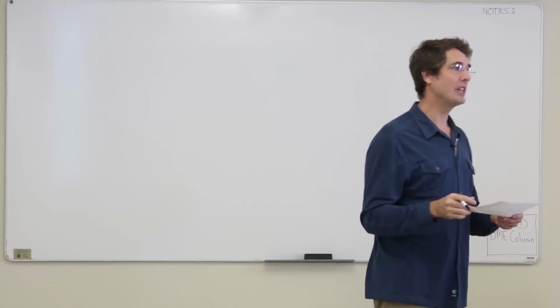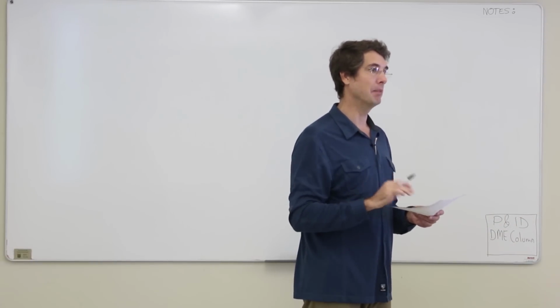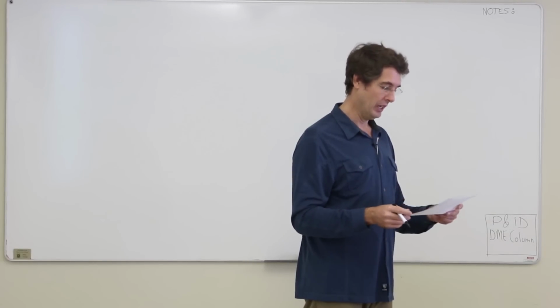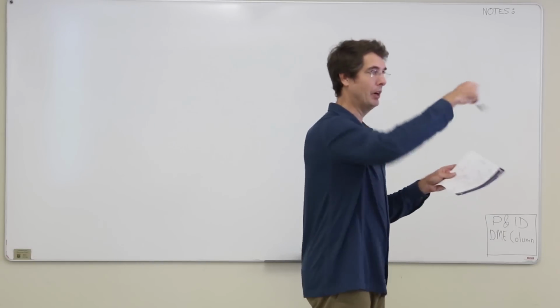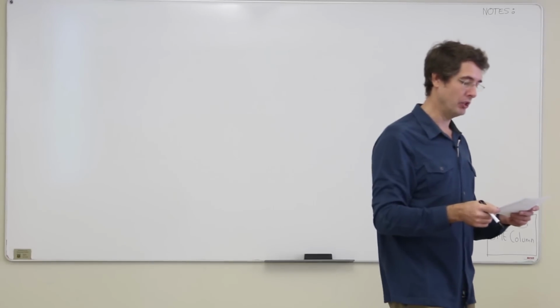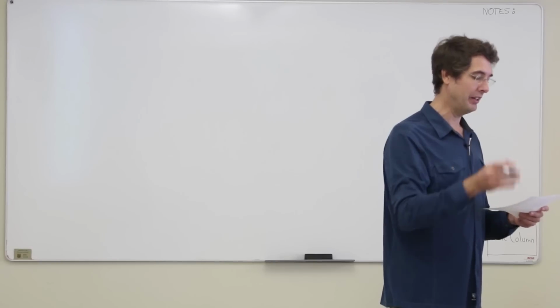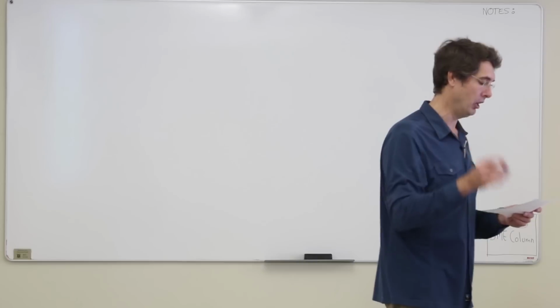Actually, the real first step in this is to sit down with the process flow diagram and start putting the controls into the process flow diagram. But then when you want to draw the P&IDs, you start with some sketches here, because very quickly I start to box myself in and I go, oh, I'm running out of room, and I'm running the line all the way around and stuff like that. You do that on a couple of 8.5 by 11 sheets, and you'll get to the big sheets, and it'll look pretty nice by the time you're done, because you got it planned out a little bit better.